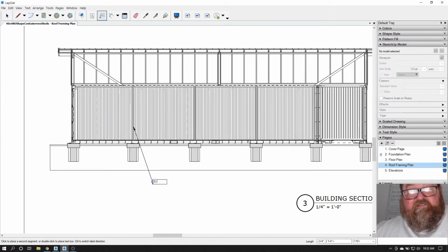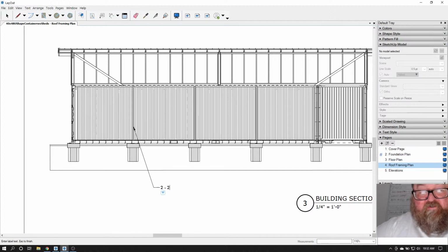Is that these are, let's see, 2x4s. You could use 2x4s or 4x4. And the reason I'm saying 2x4s is because you're already going to have 2x4s there. If you already had 4x4s, then you'd use those. Two 2x4s. They're basically at 10 foot on center.